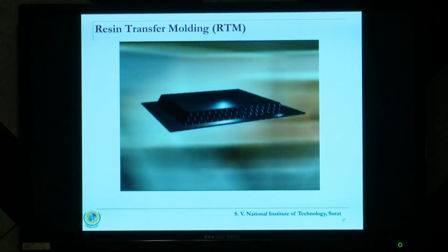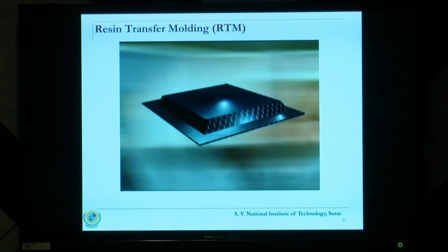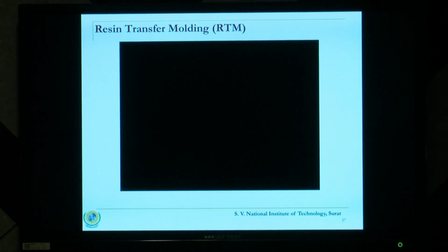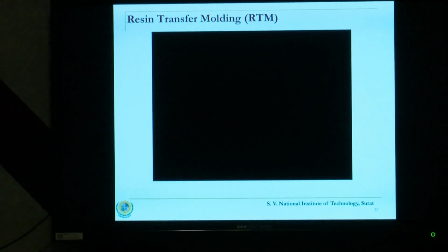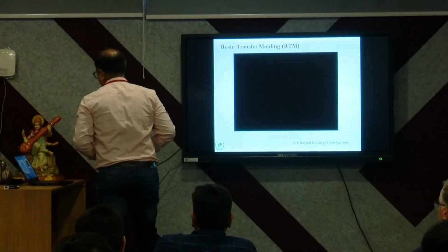So rather than that being an option, pulling becomes a better option. And so instead of RTM, vacuum infusion, vacuum resin transfer, became a better option, because once you create this vacuum, in a way that vacuum is pulling the resin inside, and once it gets filled, you can always stop. So rather than pushing this, it is better that we go for pulling it inside.